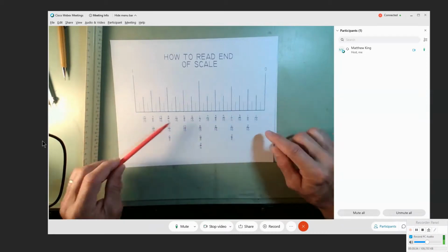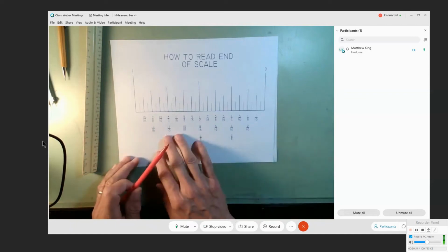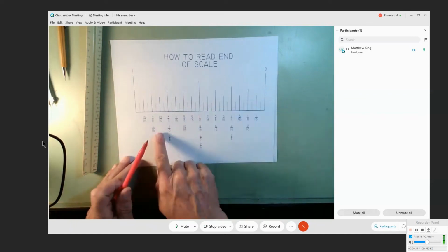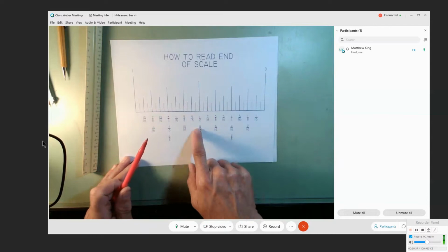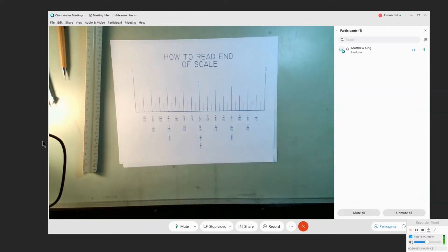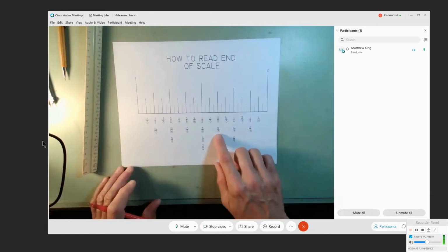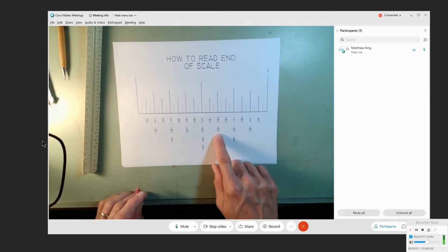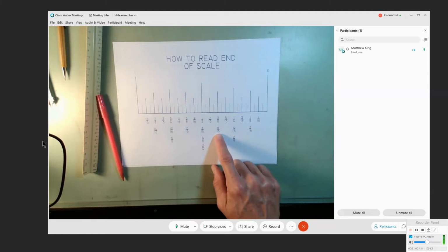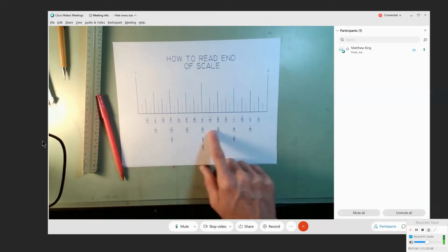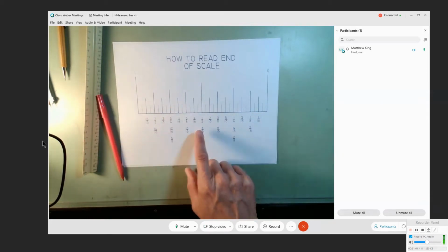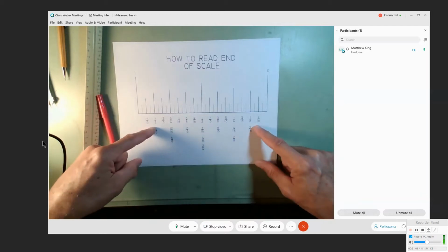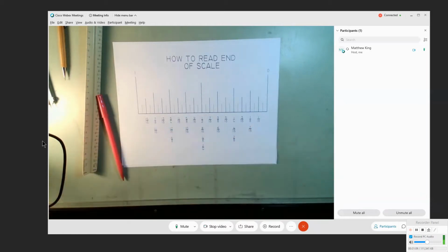As a matter of fact, any of these on the second, third, or fourth tier are just to help you locate, but you should never write or verbally describe them. That will discredit you to somebody listening to you and saying, what do you mean 6 16ths? That's supposed to be 3/8, right? That says you're saying in so many words, I don't know what I'm doing by calling it 6 16ths. So in your inner voice in your head, absolutely, whatever it takes to get you there. But outwardly, never say anything or write down as a measurement from the second, third, or fourth tier.